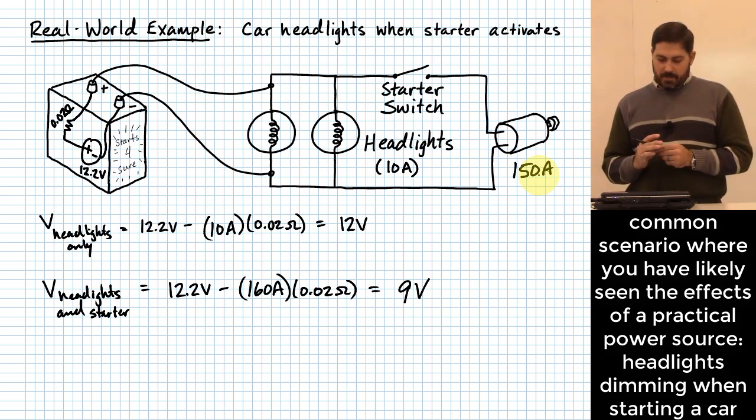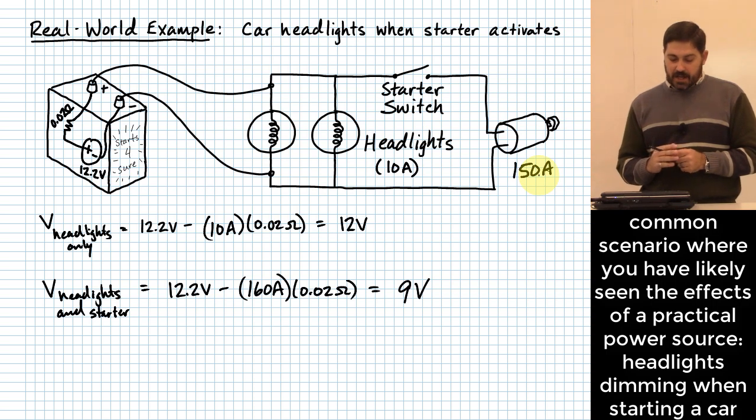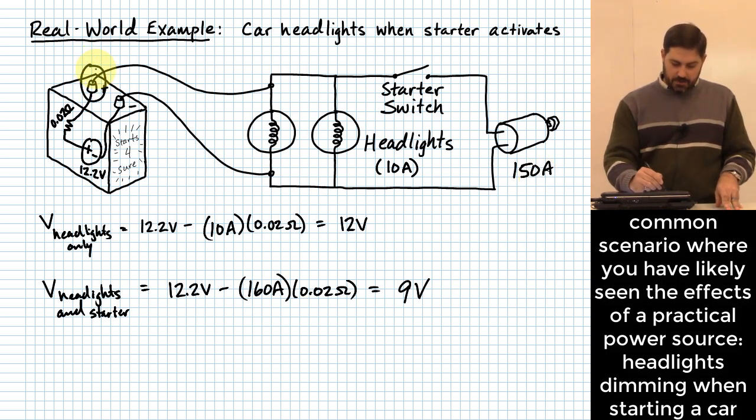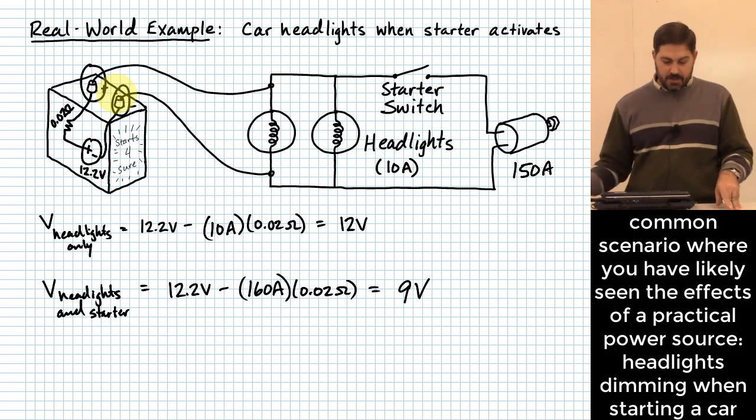All right. By the way, there can be other resistances in line too. Some of you might have dirty battery cables. What is that going to do? Like right here where you've got your cables connected, instead of there being zero resistance at that connection point, you can have a little bit more resistance right there. And what's that going to do?